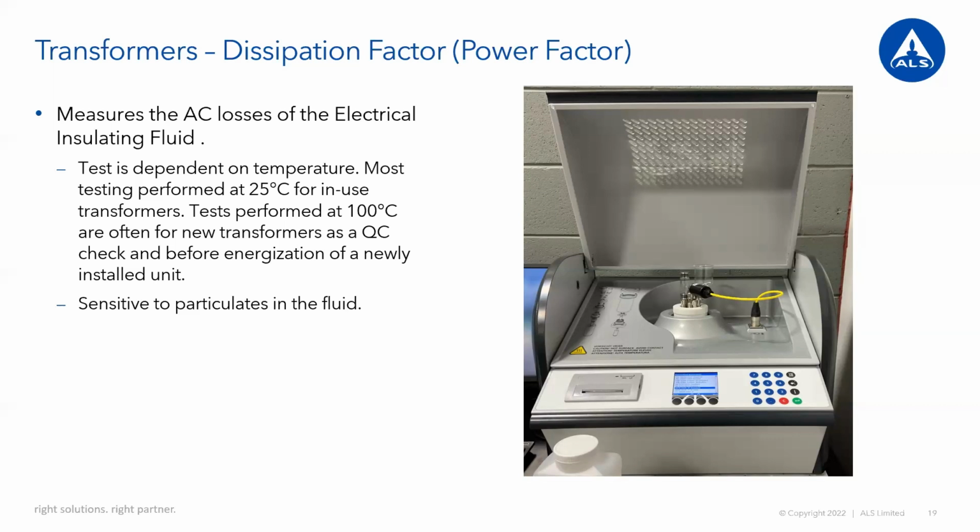Every 3 degrees above the recommended operating temperature will actually decrease the life of the transformer by half. So it's best to try and make sure that you run it the way it should be. And this is also very sensitive to particulates in the fluid.